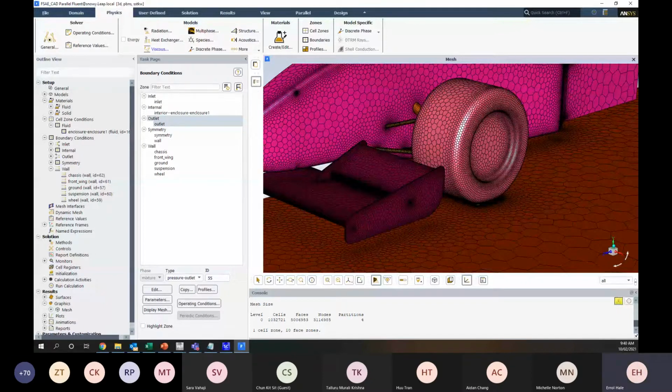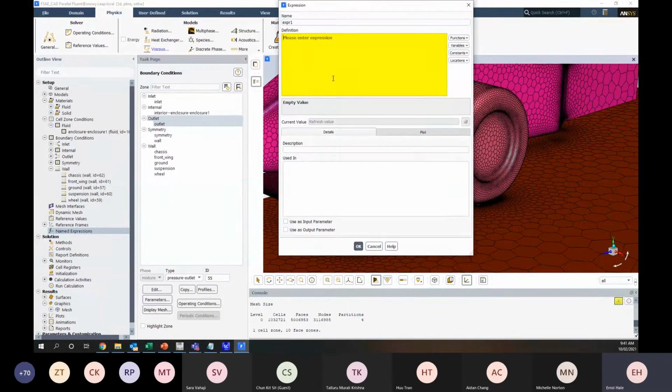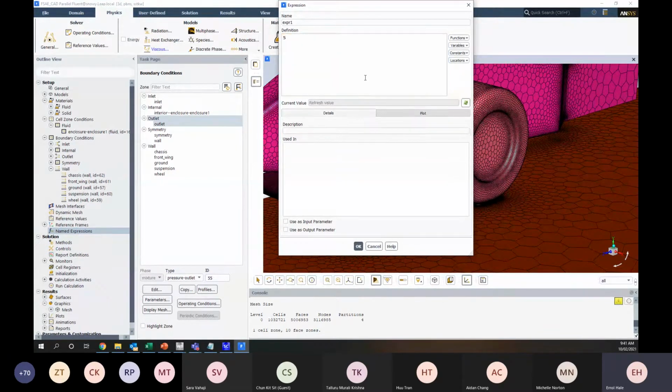For the inlet pressure condition, inlet boundary condition, are you able to set the value to vary? For example, head pressure across a large pipe under gravity flow? Yes, we can. Fluent is updating its named expressions all the time. So in the latest release, they did some really great work with making these named expressions even more useful. And these named expressions can be used to specify varying inlet conditions. So basically, if we wanted to have an inlet that varied in velocity with the increasing distance from the surface, we might have